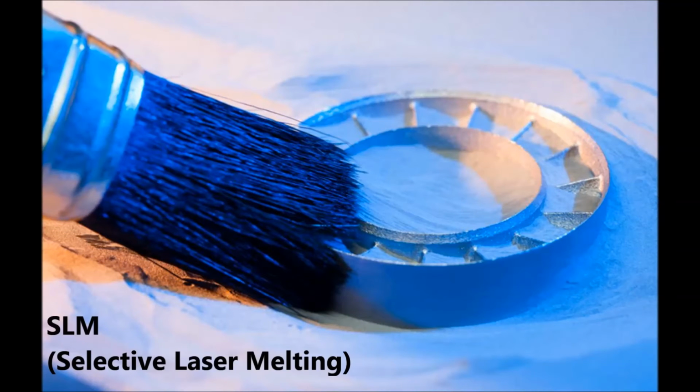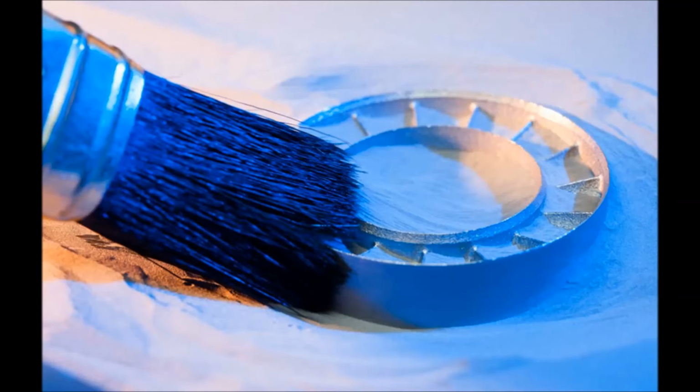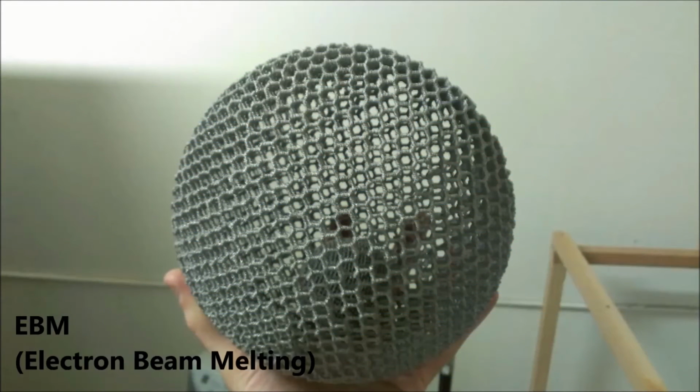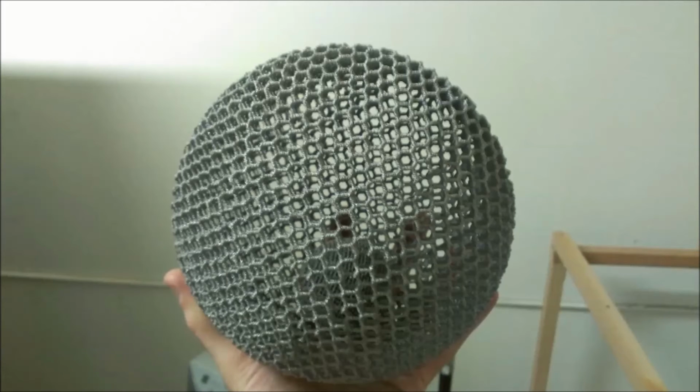SLM, or selective laser melting, is very similar to SLS but actually melts the powdered material, usually a plastic, when fusing it into a solid shape. Both SLS and SLM printers are fairly expensive because they require high-powered lasers to work. EBM, or electron beam melting, as its name suggests, uses an electron beam for melting powdered material, usually metal powder, instead of using a laser. In other respects, it is similar to SLM and SLS printing methods.